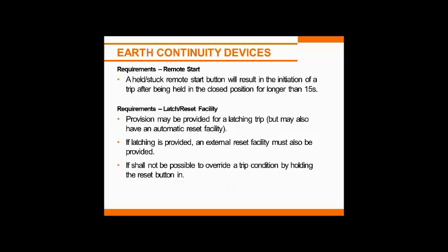Another requirement for the earth continuity relay is that if you have a remote start, and on the next page we have a drawing where we show how it's connected, that if the remote start button is stuck in, then the relay will trip after 15 seconds. And that's done on our latest relays. Earlier relays didn't take that into account. Certainly the latest standard requires that.